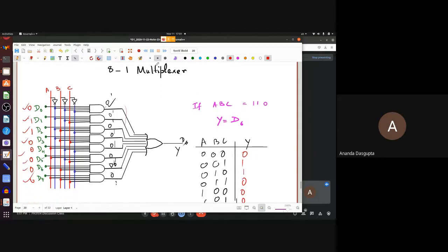A 4-input multiplexer, not demultiplexer. A 4-input multiplexer would be essentially a 16 to 1 multiplexer. And 16 to 1 essentially means that it's going to be able to reproduce 64,000 different circuits in one. But does that mean that you don't have to learn about other Boolean circuits at all? The answer is no. You do have to learn about other Boolean circuits for the simple reason that this may not be very efficient. There are much simpler or cheaper ways to create most 3-input Boolean circuits. Not this one. Okay? And could be faster. The circuits could be faster if you make it differently.